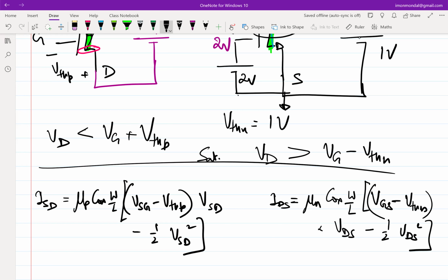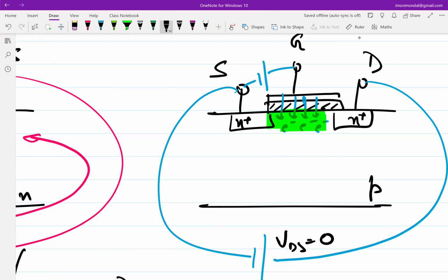Okay, so let's explain it from this perspective. Let's say the drain voltage has increased. His question was to just revisit the saturation region condition. So let's say the drain to source voltage is 0. In that case, the channel charge is symmetric. We are okay with that? So if the channel charge is symmetric, we have enough channel charge both at the source and towards the drain terminals, which means it's in linear region.